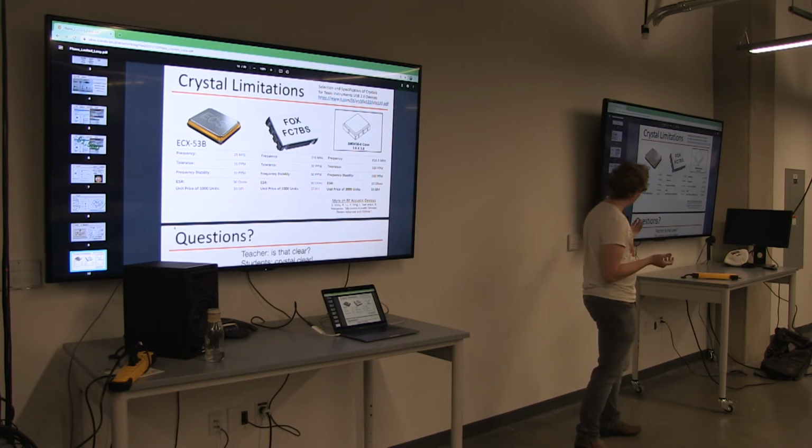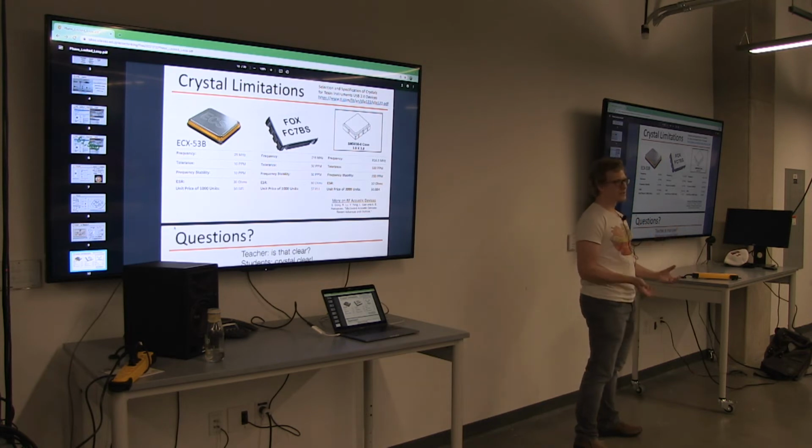And then your frequency stability, right? Like I said, the quartz crystal is really well compensated across our everyday temperatures, like 0C through 50C, very generous, but that's a good temperature range for electronics. Now, other piezoelectric materials are not so well compensated, and so they're going to have a bunch of frequency variation across temperature. It's hard to make those cuts again to compensate for that, so we're still developing that kind of technology.